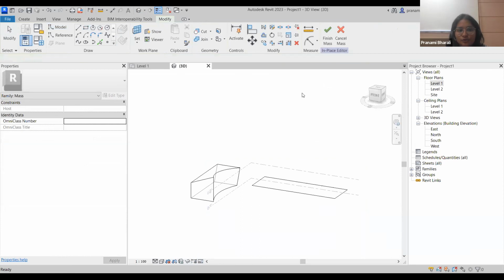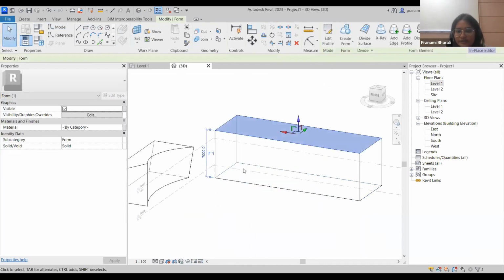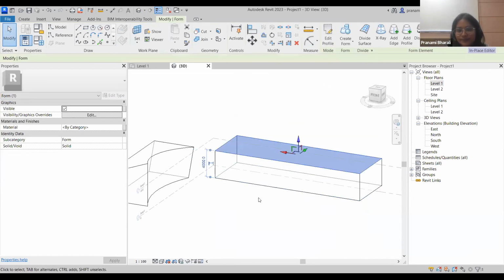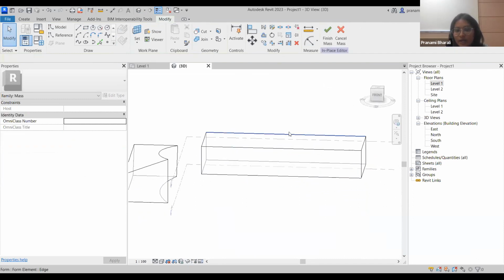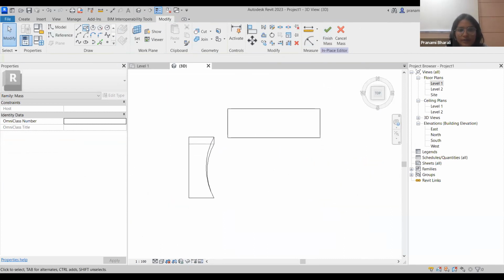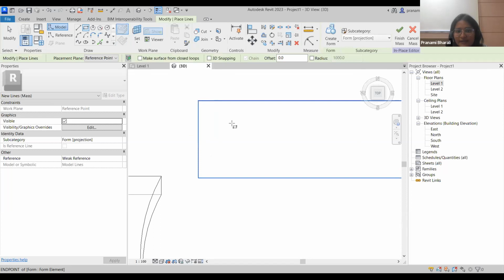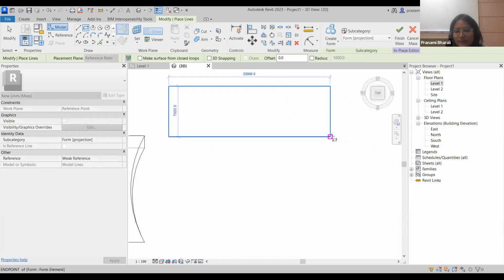And I will just go to the 3D, and in the 3D I'll just go for the same procedure as creating this, right? I'll just make this as maybe 4 meter only. Okay. And now what I will do, upon this face I want to create another one. So for that, again I can go for the rectangle option only, suppose. And in the rectangle option, instead of using the work plane, I'll just go for the face option in here. Okay, the face will highlight this face, as you can see, and I can create another rectangle upon the same.